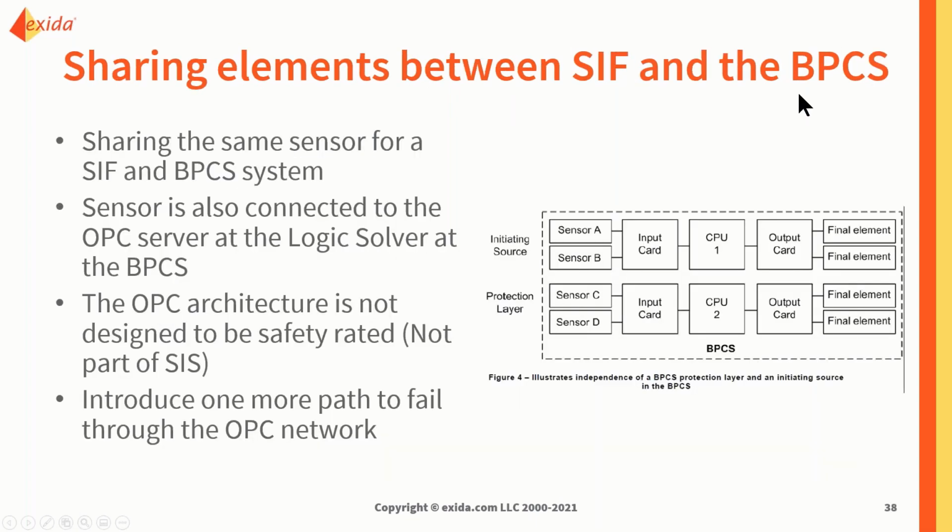The other problem that I see would be sharing elements between the SIS and also the BPCS. This is a problem not just for OPC, because whenever you do that, you're not compliant with the IEC standard.